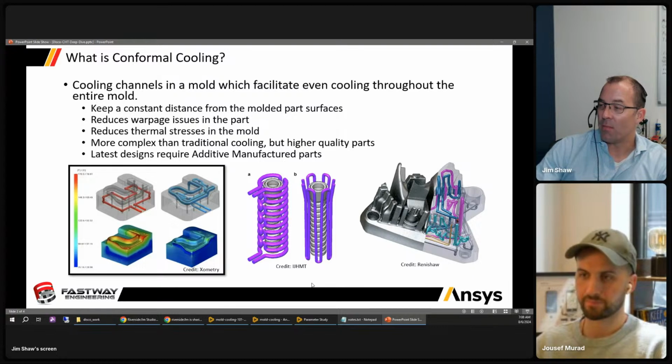So let's take that one step further. This is from the International Journal of Heat and Mass Transfer. We're looking at what are the variety of different ways now, right? So you can say, hey, I've got this cylindrical geometry. It looks like it's got a sort of a screw thread on it. I can conform to that geometry several different ways. I can spiral around it. Here I've got, looks like 2 inlets, 2 outlets, same thing on this side. Maybe this time I go circumferential, this time I go axial. There's so many different ways that we can create this cooling circuit geometry and try to maintain it.